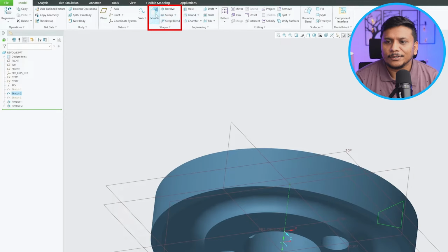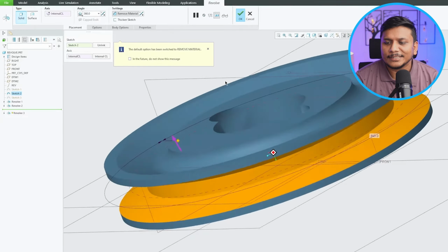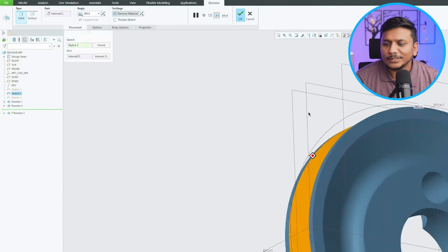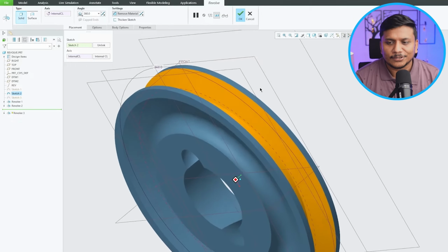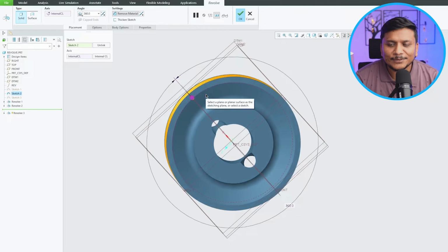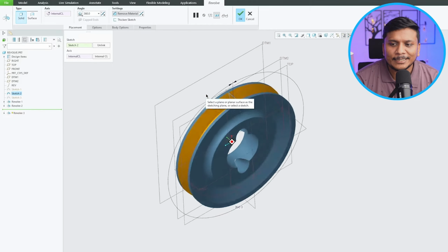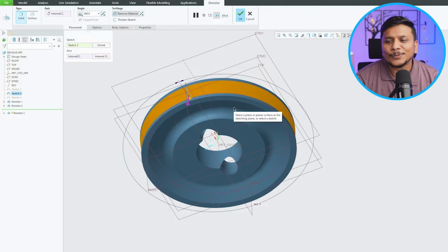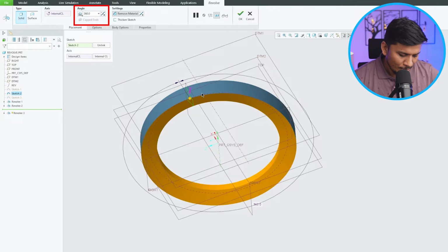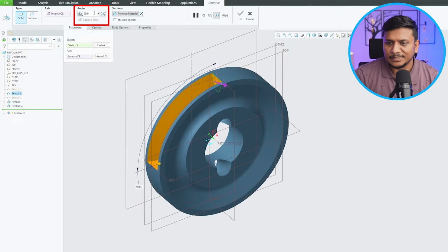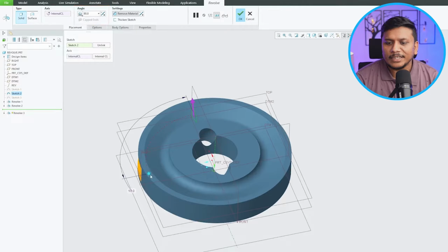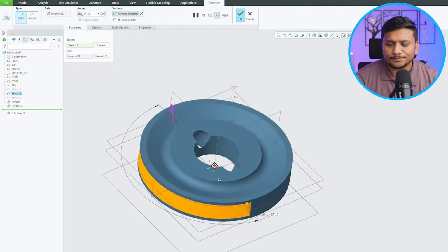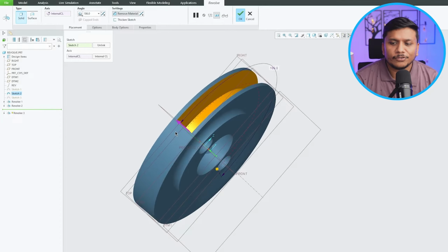Let's click here on revolve, and you can see that since the whole sketch was intersecting the solid part, Creo is smart enough to observe it, and then it offered us a remove material way. It's actually up to us whether we want to do a 360-degree revolve, or we would like to make it 90. So based on our need, we can revolve the object, and then we also have the option.